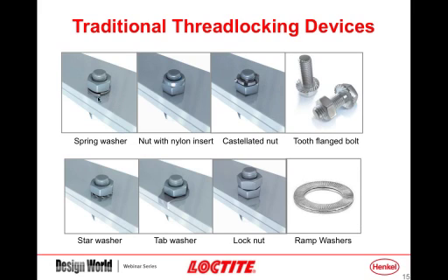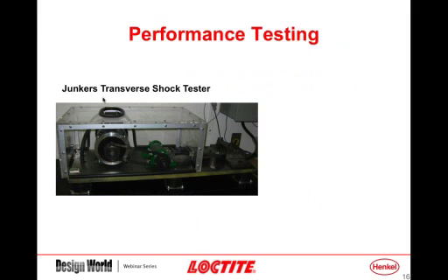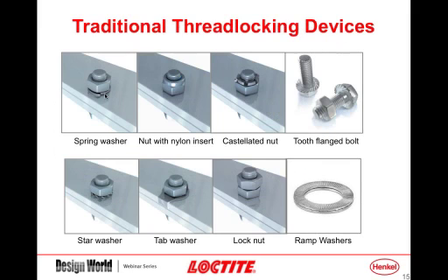And as a rule, that small amount, which can be just a couple of pounds to depress the spring washer, is not enough to prevent loosening. I know in some NASA studies that they did of fasteners, they found this to be really ineffective. It's more of a bearing surface than a thread locking device.